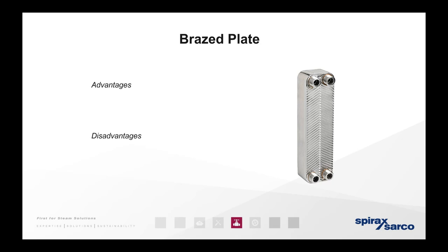Abdi is asking, we're experiencing challenges with our plate heat exchangers in terms of thermal consumption and heat transfer efficiency. Specifically, we have observed higher than expected thermal consumption, which indicates that the system may not be operating optimally. Despite setting the desired inlet and outlet water temperature to 75 degrees and 85 degrees Celsius respectively, there appears to be an imbalance in the steam and water flow rates through a PHX. How could we determine the proper number of plates for the optimal heat transfer and safe consumption?